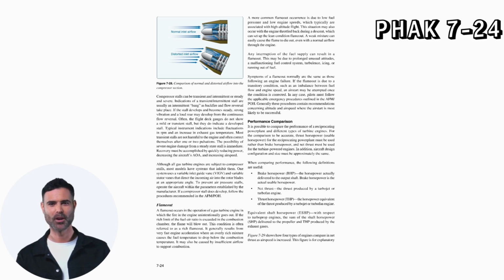A more common flameout occurrence is due to low fuel pressure and low engine speeds, which typically are associated with high-altitude flight. This situation may also occur with the engine throttled back during a descent, which can set up the lean condition flameout. A weak mixture can easily cause the flame to die out, even with a normal airflow through the engine. Any interruption of the fuel supply can result in a flameout. This may be due to prolonged unusual attitudes, a malfunctioning fuel control system, turbulence, icing, or running out of fuel.